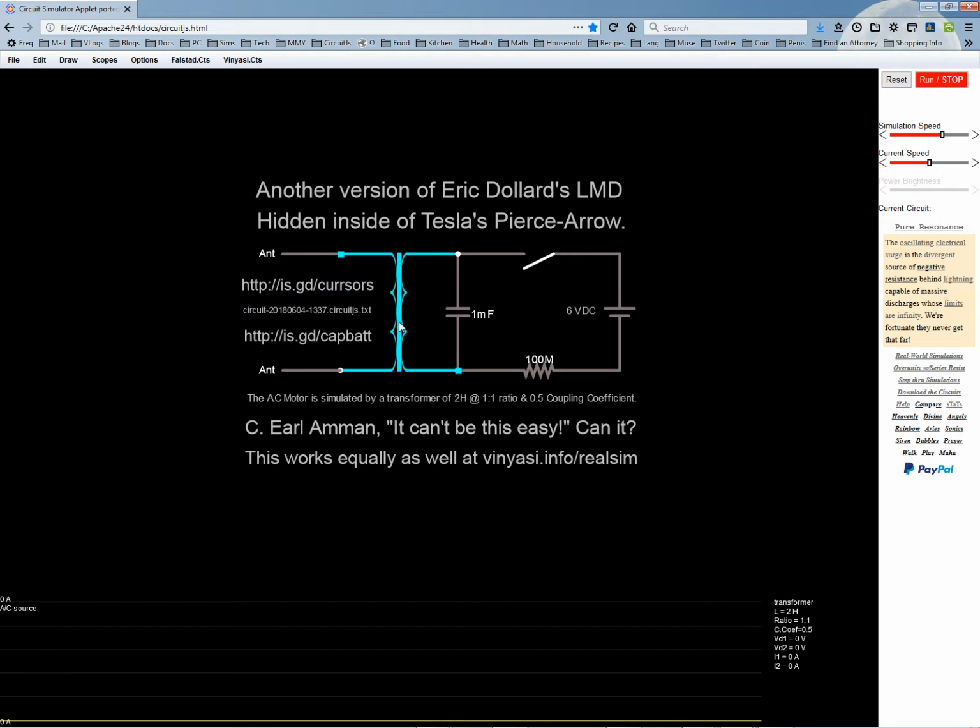Now, it's not uncommon to put a capacitor across an AC motor if that motor is a single-phase motor, in which Tesla actually invented a self-starting AC single-phase motor by adding an extra pair of coils. He'd have a pair of coils opposite each other, and the thing would just wiggle back and forth due to the nature of AC current. But then, at right angles to that, he put another pair of smaller coils opposite each other, and that got it started in one direction or the other.